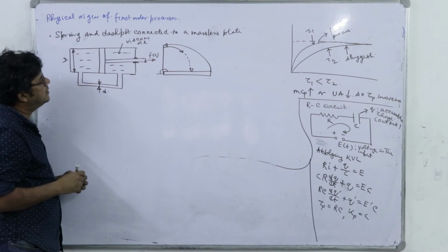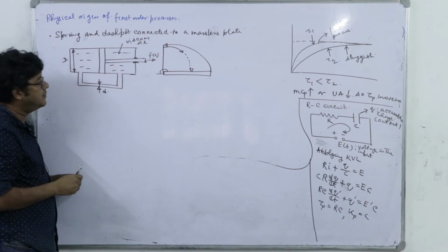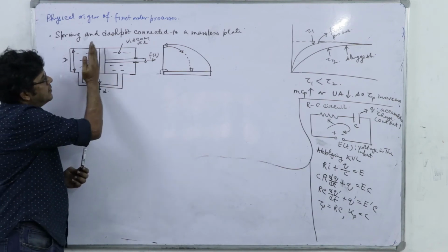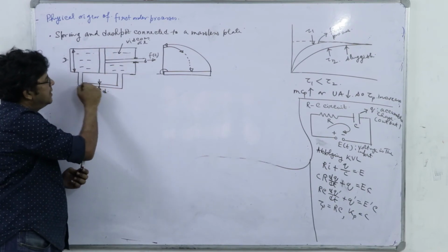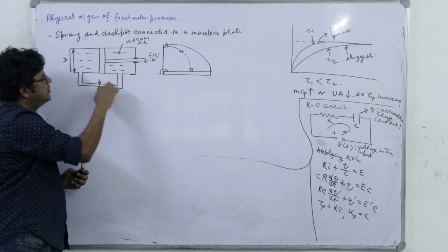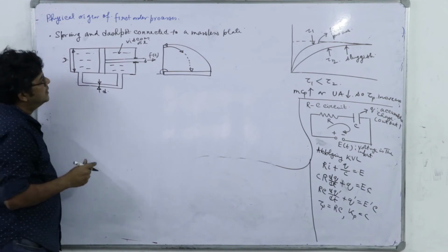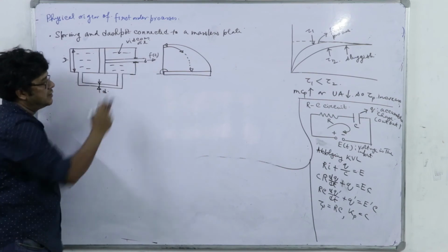which divides the entire cylinder into two compartments which are alternatively connected sidewise by a capillary of diameter d, what will happen? The piston can only move to the right-hand side if oil is moving with an equal amount of volume displacement through this capillary. Correct? So let's calculate the velocity of oil through this capillary, how it is related to the force.